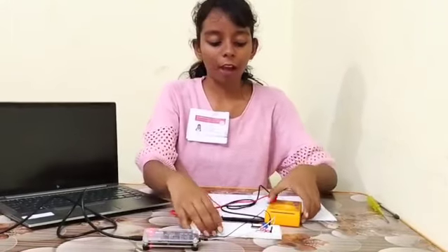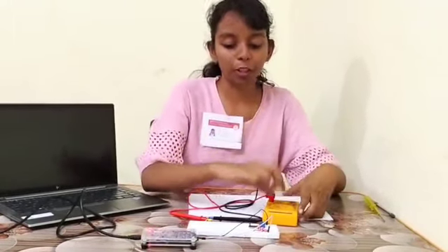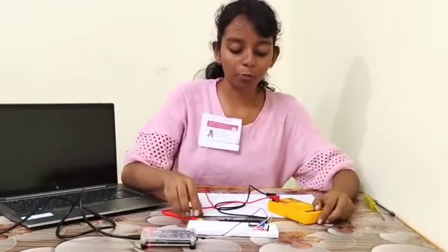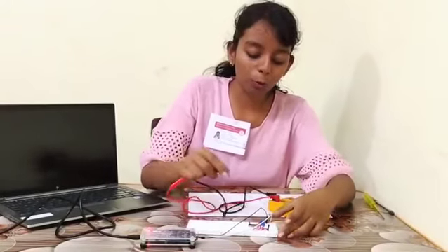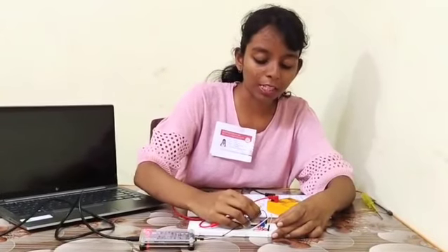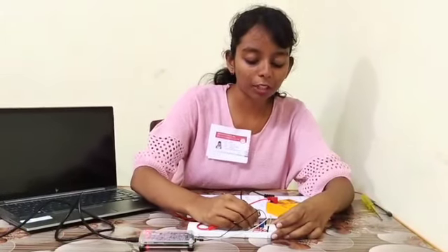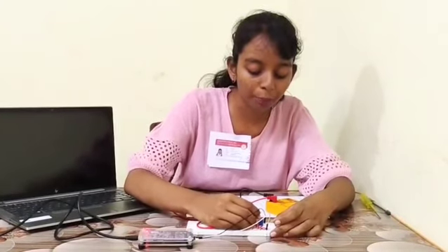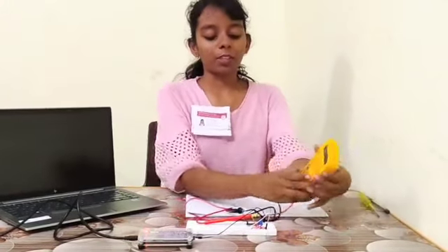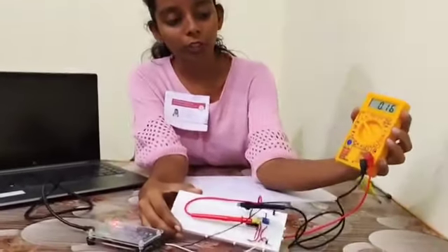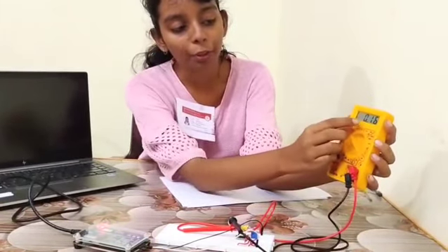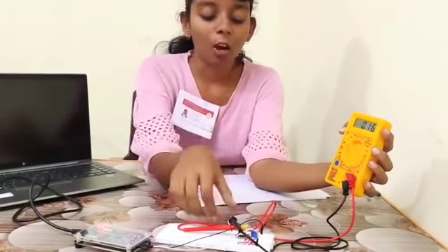And now we have to take the voltage reading, the V input, which is necessary so that we can plot the VTC graph. So we'll be connecting this to a voltmeter, and we will connect the black probe to the ground, which is adjacent to the IC's pin 7, and the red probe to pin 2, which serves as the input voltage source. From this connection we observe that the voltage reading happens to be 0.16 volt, which is the V input.